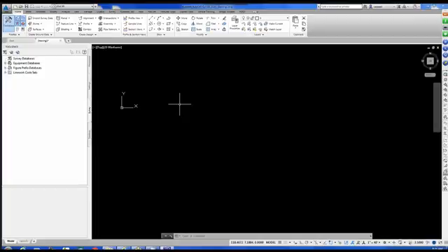now, the first part of the process is that we have to tell the software where you want the survey database to be stored. The way that we do it in Civil 3D is we select on survey database. Many of you have heard me say this before: when in doubt, right click. All right, so I'm going to go to the survey database, right click, and say set the working folder.